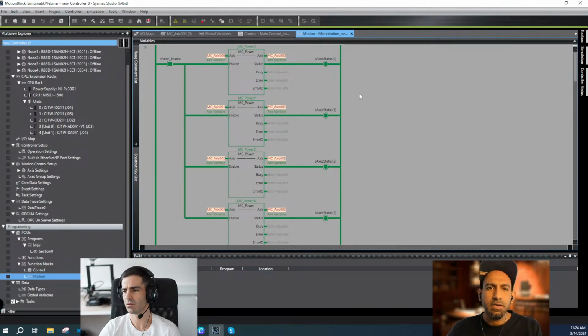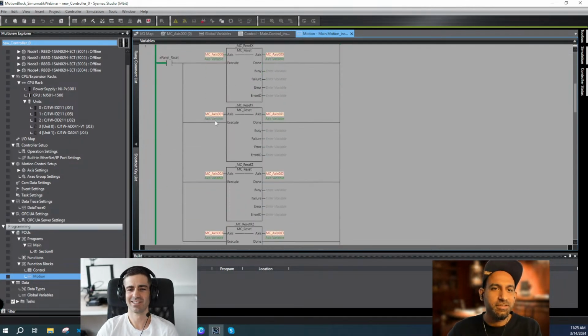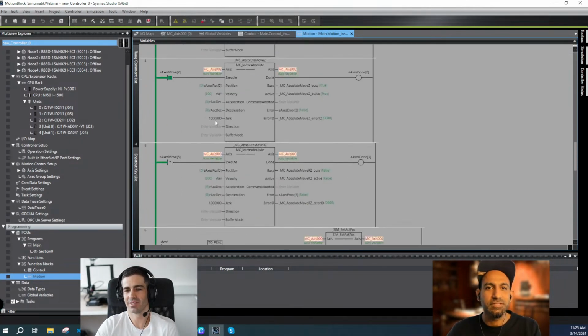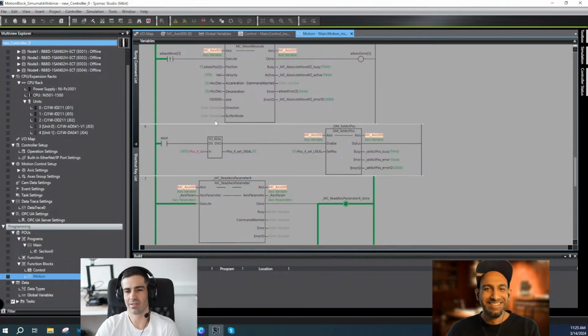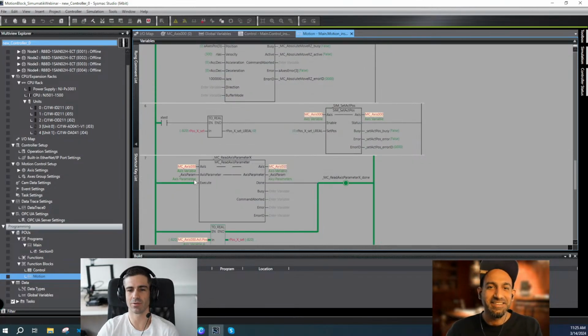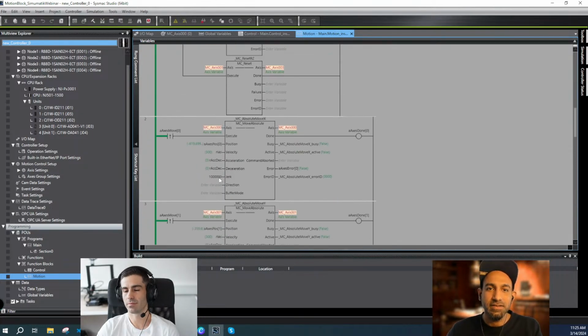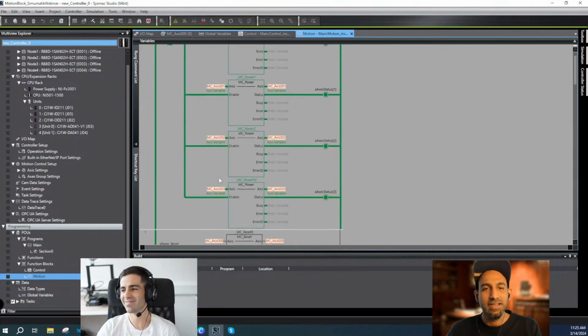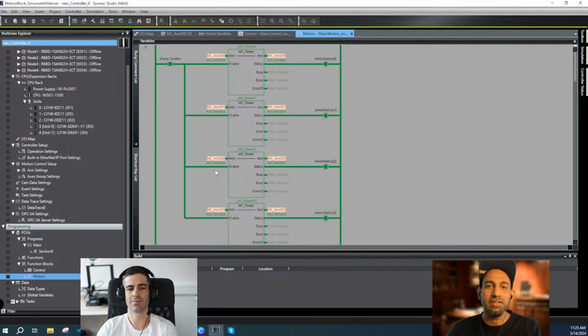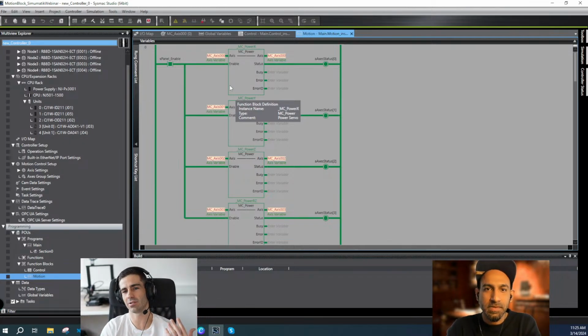Right? Oh yeah, yesterday I tried at 4 o'clock, and then I think in 3-4 hours I could do it, with all the testing and integration and some bugs. It was great. I mean, it's awesome that you can do it so quickly. And it's also only because I had the structured text ready in Codesys. I just needed to copy paste the sequence. Otherwise, writing a sequence is also big. It takes more time. But it's pretty cool. So porting code, I think, is going to become easier and easier between different platforms.